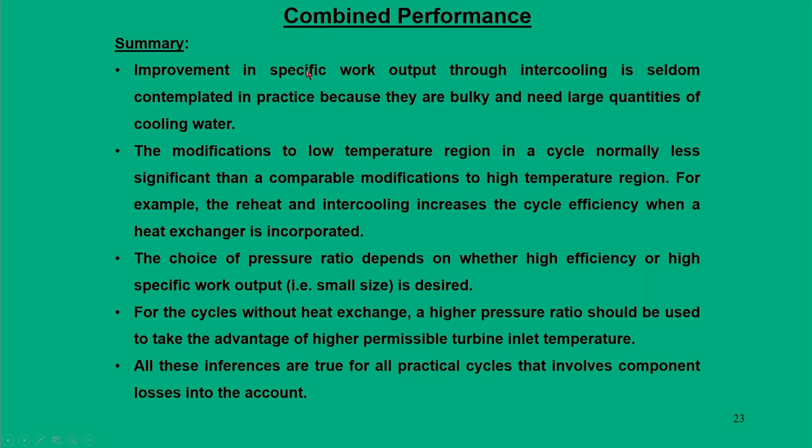So, if you want to summarize what we as users should do: the first thing is that improvement in the specific work output through intercooling is normally not recommended, because the intercoolers are bulky and need large quantities of cooling water in a typical gas turbine plant, although thermodynamically it is one of the very viable options to reduce the compressor work.